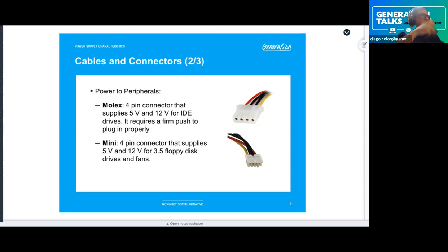I would disconnect everything, even the P1, turn it on, and see if the PSU reacts. Please, obviously, connect the little power button to the motherboard. Humor me on that part. Then turn it on with the soft power button. Then go ahead and put in the P1, which obviously has to be in there, and any other connector that you want.